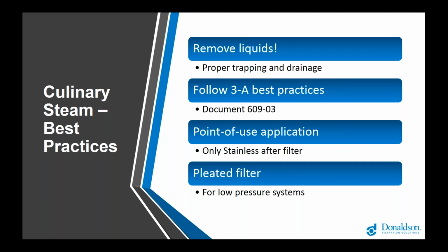It also helps to pay close attention during system startup to ensure that the entire system is brought up to heat in stages. So slowly bringing up the temperature is going to avoid the entire system from becoming overwhelmed with water and ultimately causing problems. So next, follow already established guidelines like the culinary steam best practices published by 3A. It contains all the useful information that's needed to produce a proper system and will avoid any important steps being missed. It's something that's easily available online. It's reasonably low cost. There's really no reason to not use something that's already been developed to try to cover all of these bases.